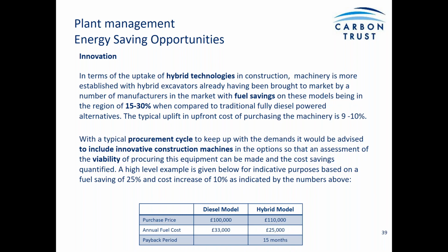So there's a basic case study there, just looking at the opportunities for the uptake of the hybrid technologies. The kind of fuel savings you could expect are in the regions of the 15 to 30%. Obviously, it's going to depend on how the machine is operated.